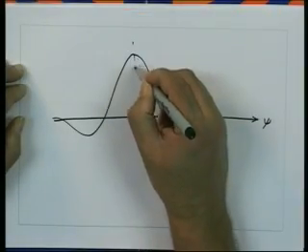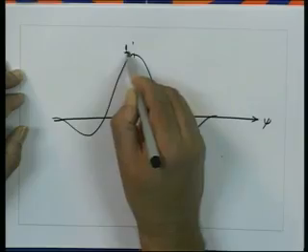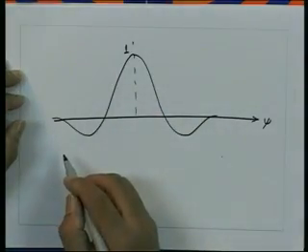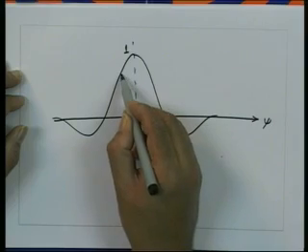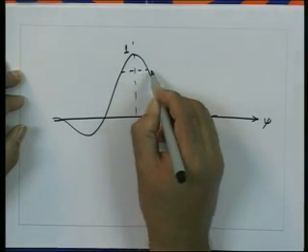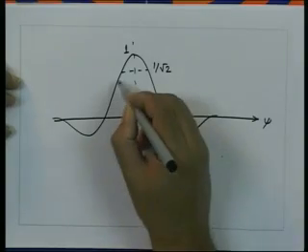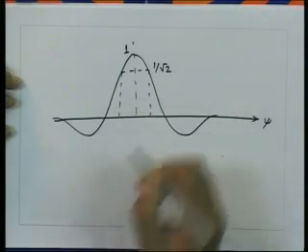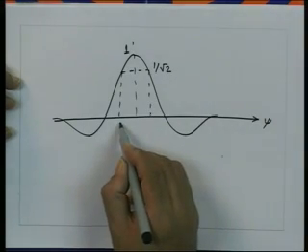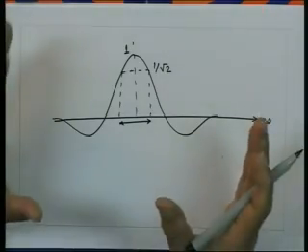This is the direction of the maximum radiation, and if I take the 3 dB points of this radiation pattern, that is when the electric field goes to 1 over root 2 of its maximum. If I take these 2 points where this is 1 upon root 2, we can find these 2 directions, and this angular width would give me the half power beam width.